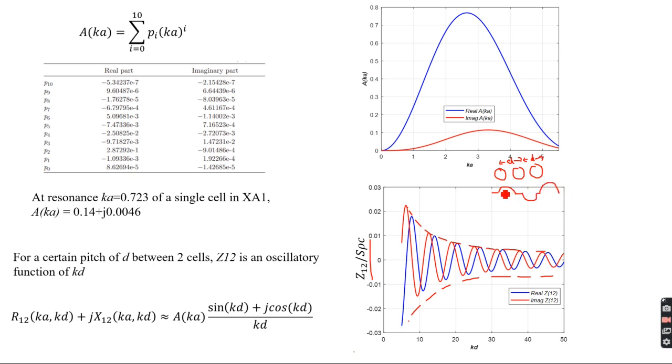The first and third cells push the second cell to go 180 degrees out of phase, so it goes down and experiences a negative radiation impedance, vibrating out of phase with respect to the other two. That's the idea of negative radiation resistance when you consider the coupling of cells in an immersion medium.